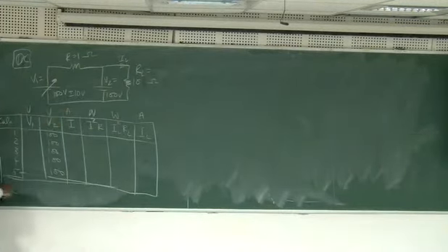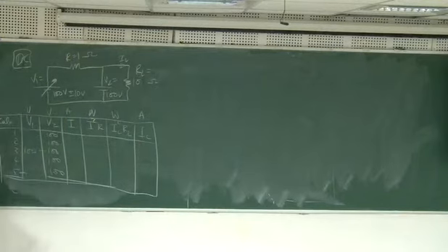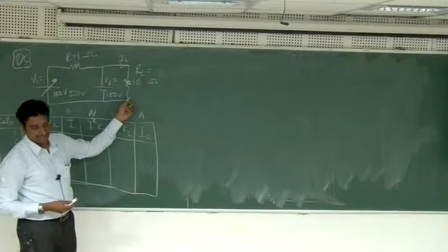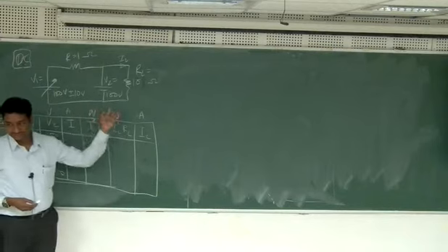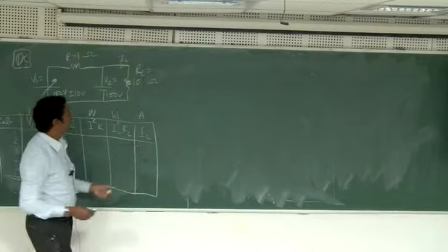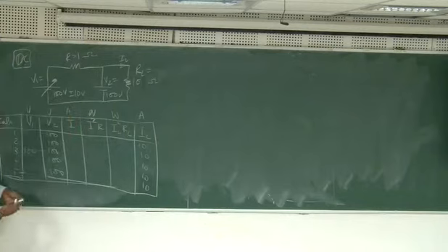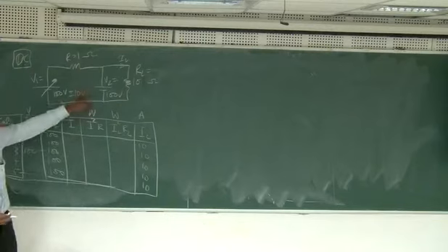Let's start with case 3, where both these voltages are equal. So my question is, what is IL first of all? Because this voltage is fixed at 100 and then immediately it is 10 ohms, IL is always fixed, irrespective of the value of V1. How much is IL? 10 amperes. 10, 10, 10, 10, 10. Variations of V1 do not affect IL. V1 keeps on varying, but IL remains fixed.